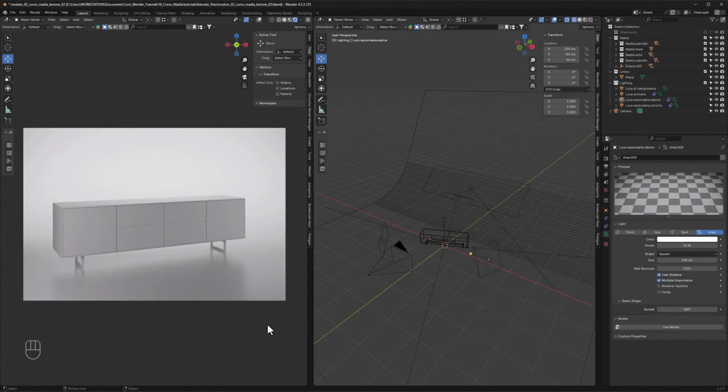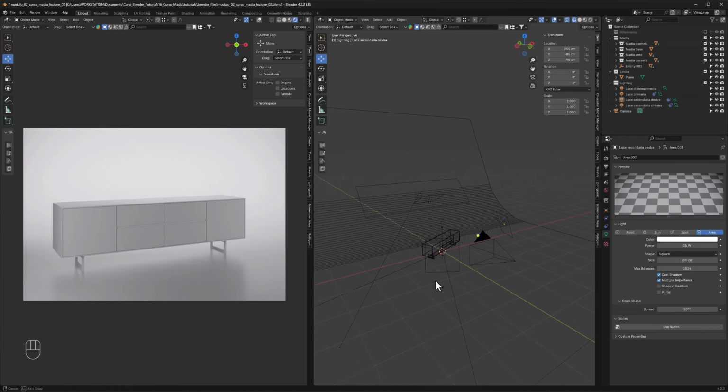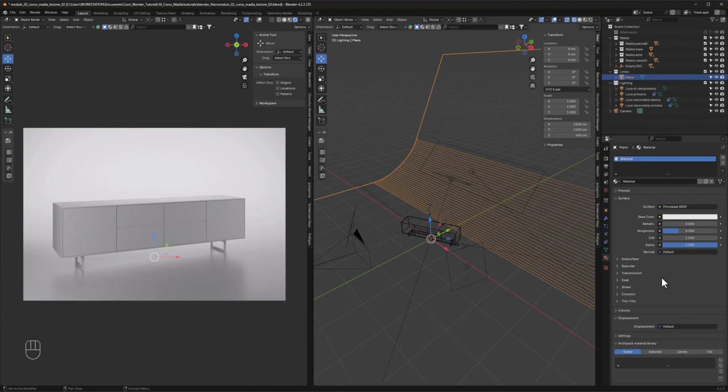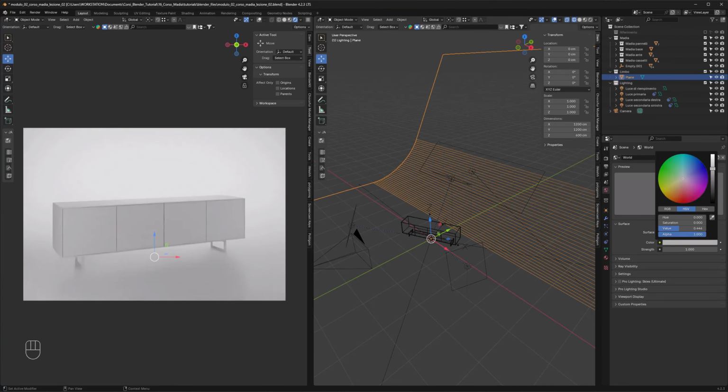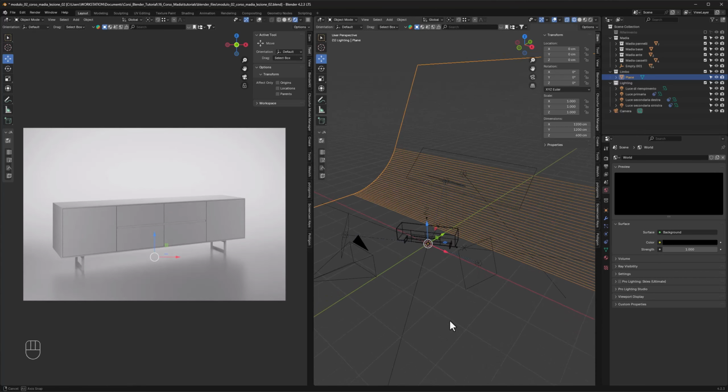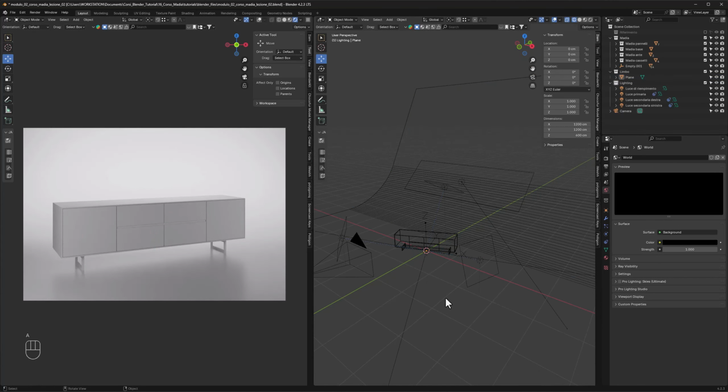Even though the result we've achieved is definitely good, we're not done yet. In some cases, it may be necessary to have greater control over the contact shadows and reflections. Therefore, we need to make this factor manageable. We could solve this by reducing the reflection parameter of the limbo material, but this operation would lead to a noticeable change in the entire scene. Alternatively, we can turn the ambient light back on, but as we can see, in addition to reducing reflections and shadows, this results in the scene being overexposed. So once again, we solve the problem with a photographic approach, and we do this by adding a fairly large light that illuminates the entire scene from above.